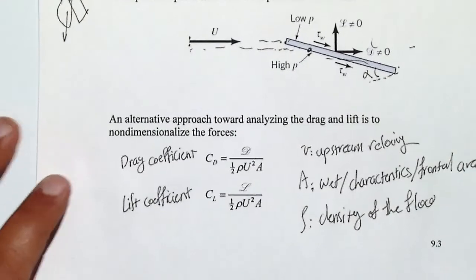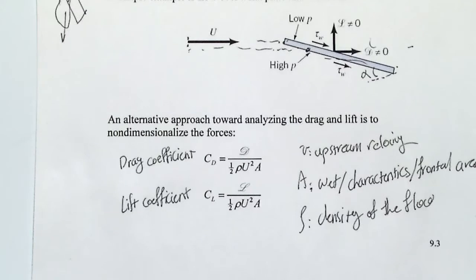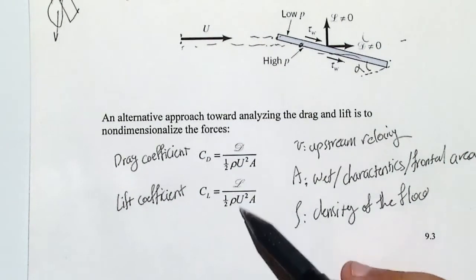So as long as you have the drag coefficient and lift coefficient for an object, then based on the area that the object has, meaning the scale of the airfoil. For example, the airfoil that you have in scale 1, and you change it to a higher scale, then your A is going to change, right? Then absolutely the drag force and lift force are going to change because the area is going to change. Also velocity is part of that.